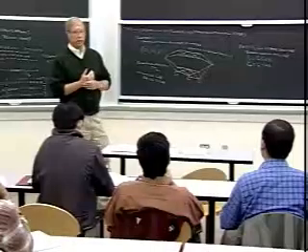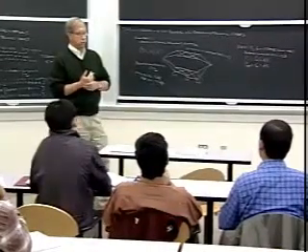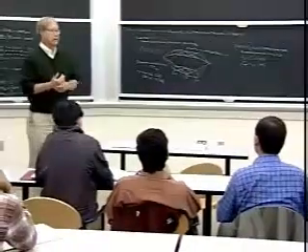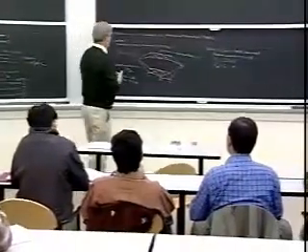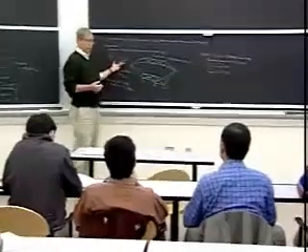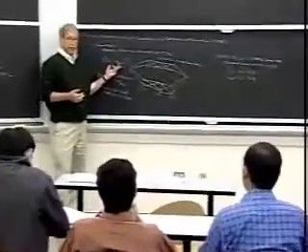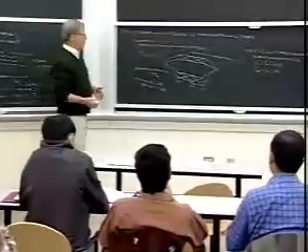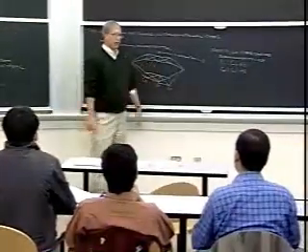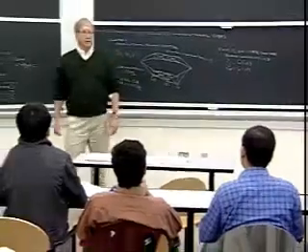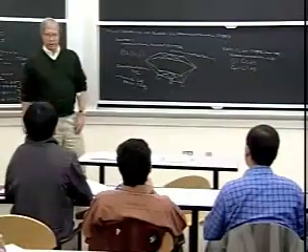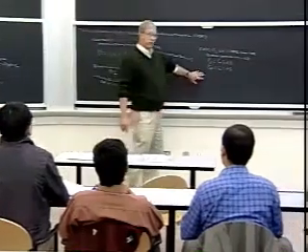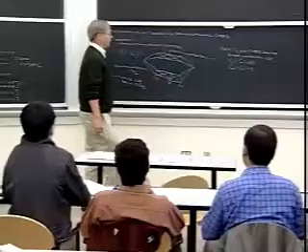And sometimes you want block codes for other reasons. Sometimes you want short blocks. Sometimes you're limited to a block of less than 100. And in that case, you're certainly not going to do better in terms of N, K, D than the best block code of length 100. Why are convolutional codes better? First of all, they are naturally well adapted to the trellis idea. They are linear time-invariant machines that just have very nice regular trellises. So they're naturally adapted.